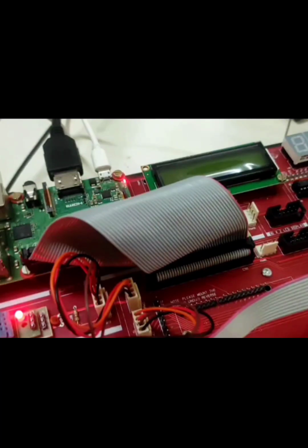Now moving ahead with the DHT. DHT is a low cost digital sensor for sensing temperature and humidity. This sensor can be easily interfaced with any microcontroller such as Arduino, Raspberry Pi, etc. The DHT has two types, DHT11 and DHT22. The DHT11 humidity and temperature sensor is available as a module, and the difference between the sensor and the module is a pull up resistor and a power on LED.